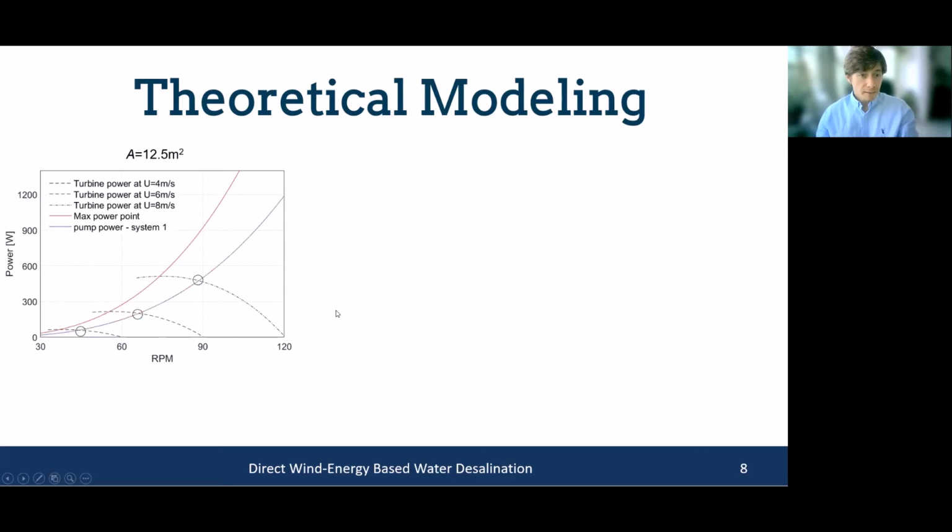So we can plan a system that will work at 90% efficiency, or 90% maximum efficiency from the turbine, meaning almost the maximum efficiency we can take out of the wind with the specific turbine. And why don't we work at the maximum? This is because this equilibrium is non-stable, so we prefer to work at 90% maximum efficiency.